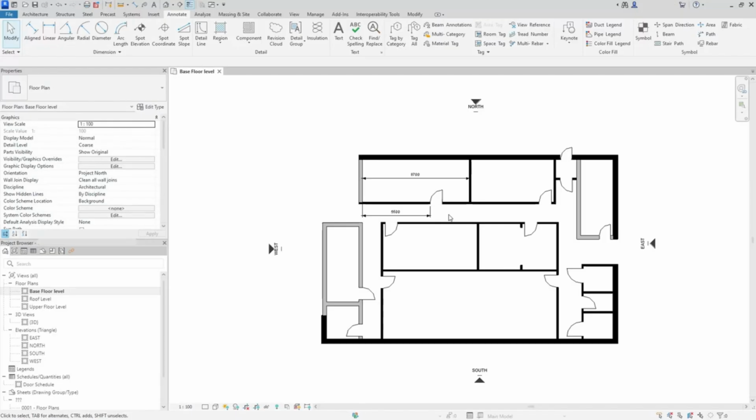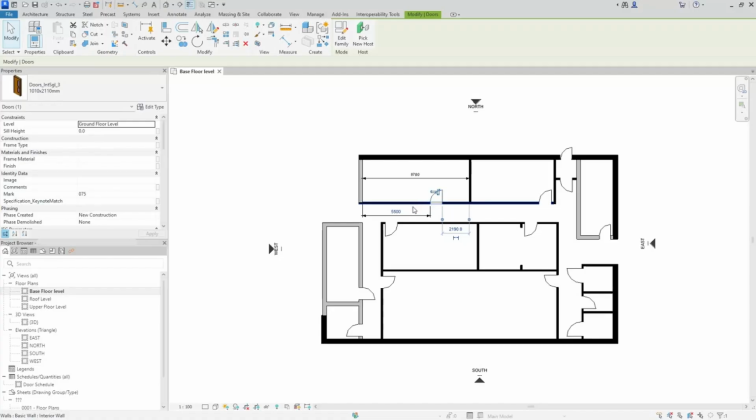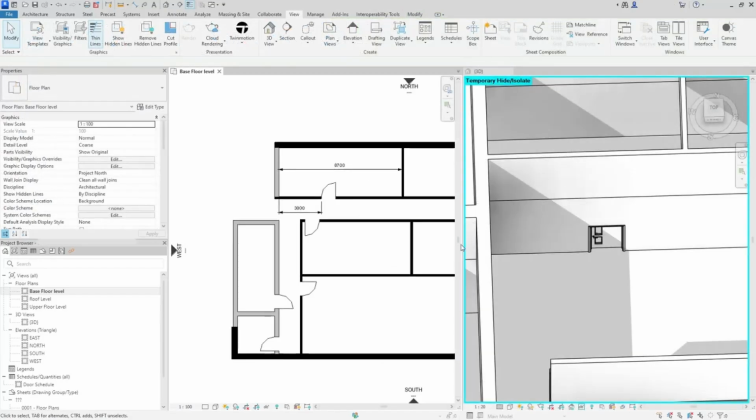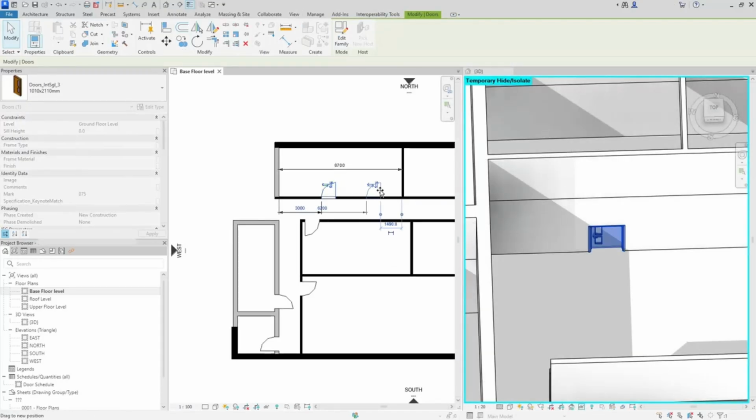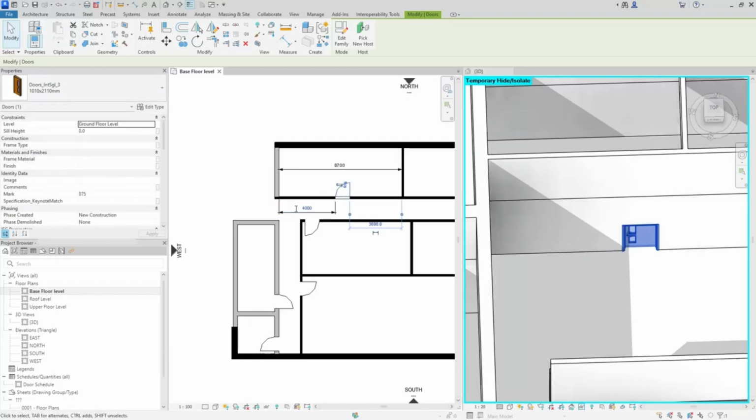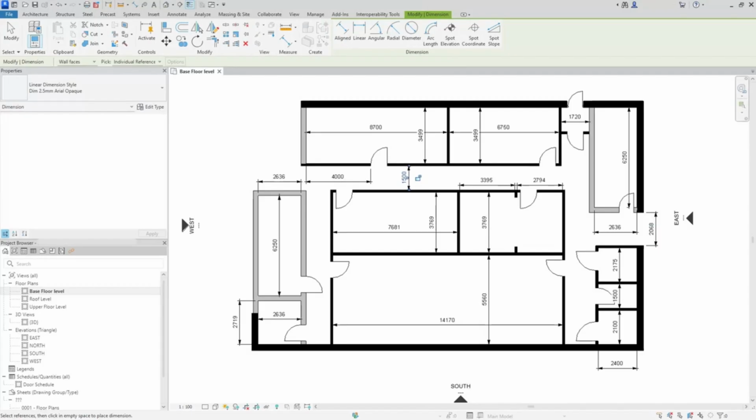The dimension provides you with an opportunity to move the door. Hover your mouse over the door and click to select it. Notice that the dimension value turns blue and looks different to the other dimensions. Click on the value and you can change it by typing in a new value, which moves the door. Dragging a door in the plan view or selecting the door and editing the dimension drives the change in every view. Continue to add the horizontal and vertical dimensions to every room.